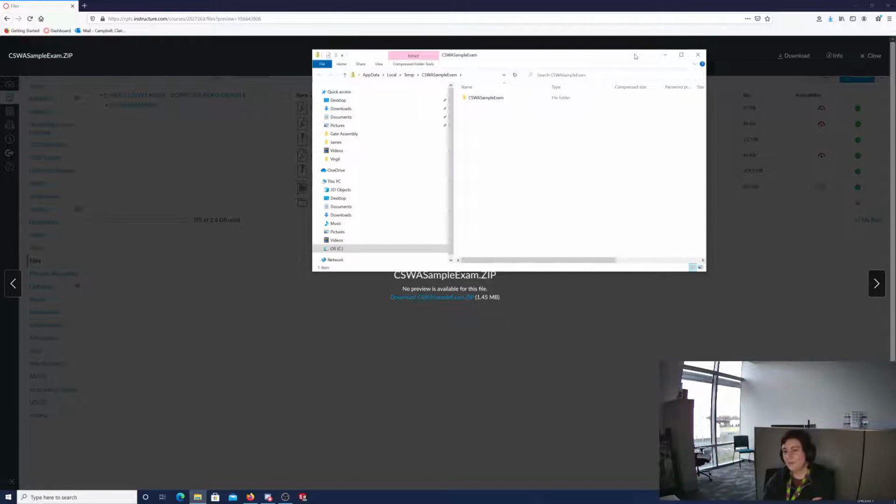Okay. So when you design your part in CAD, after you draw the whole thing, you're going to want to flip it over and change its relation to the origin, so that the biggest, flattest part is on the bottom in your design. And we'll go over that too. Once you design your first part and turn it in, we'll go over each of your assignments together.